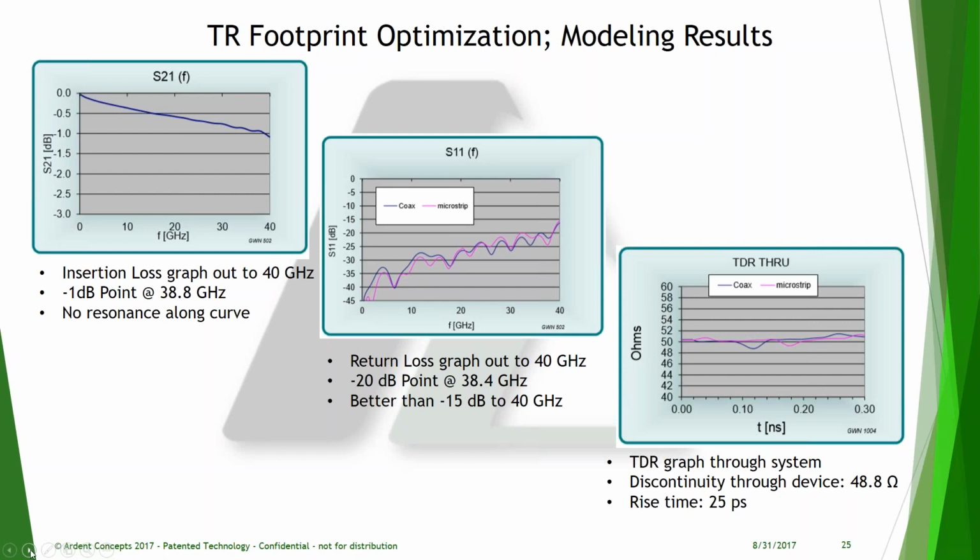Geometries that we focus on can vary based on the routing configurations. For microstrip, we'll look at the capture pads and anti-pads and narrow trace. And for strip line, we'll look at more of those anti-pads as we go through the via.